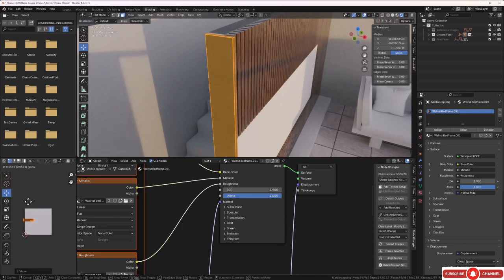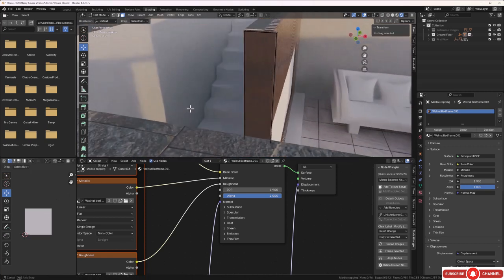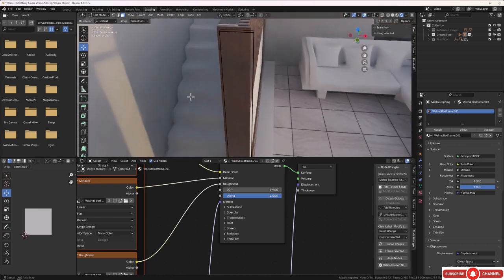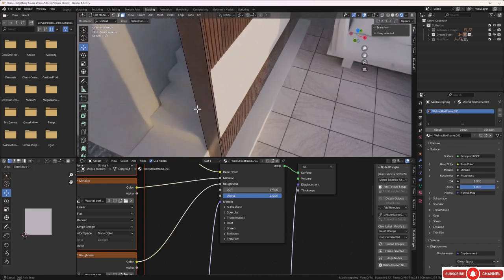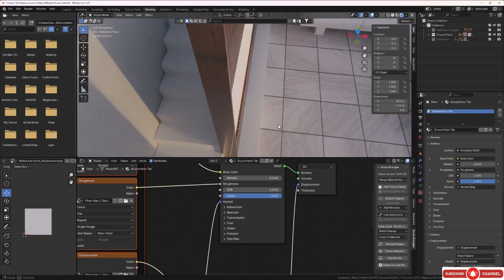See if we can eliminate that set of knots and maybe just rotate it ever so slightly. And let's see what we got there now. And by rotating it, that means possibly that that set of knots will just sort of fade out of the map because they've just run off the UV map, and that's what we seem to be getting there. I'll tap out of edit mode just to check that out. And yeah, I think I'm happy with that.